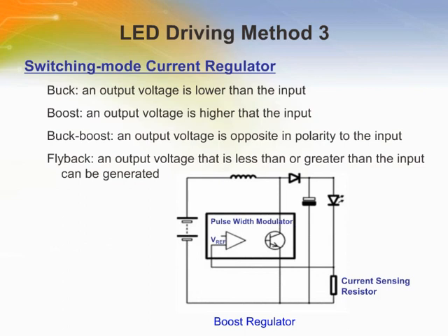The basic switch regulator uses a transistor as a switch that alternately connects and disconnects the input voltage to an inductor. The current pulses are smoothed by the external inductor, diode, and capacitor. Current feedback from the sense resistor requires more components than shown here, but the basic principle is the same. The current is compared with a reference, and the output of the regulator adjusts itself to keep the LED current constant despite falling battery voltage or rising LED temperature.